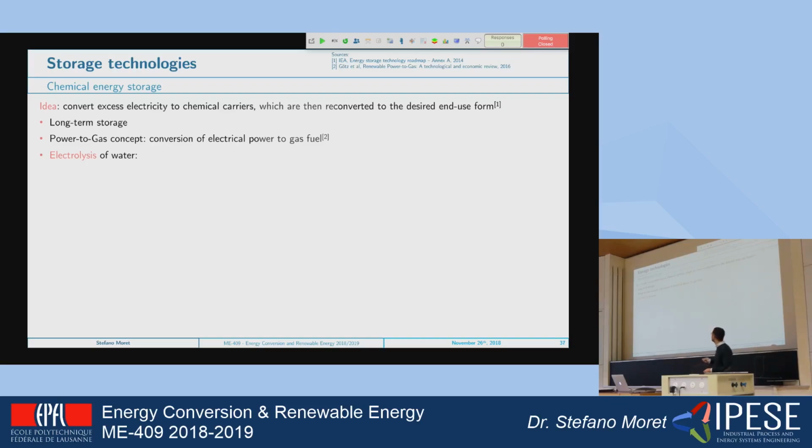It is the idea of converting electricity to fuels, okay? So, why fuels? Well, because fuels have a very high energy density. We are talking about kilojoule per kilogram up to now for the other technologies. When we have fuels, you remember natural gas has around 45-50 megajoules per kilogram. Hydrogen is even higher, okay? So storing electricity in fuels is one of the most efficient ways under the energy density aspect of using electricity. And we have technologies to do that. Actually, the technology is pretty simple.